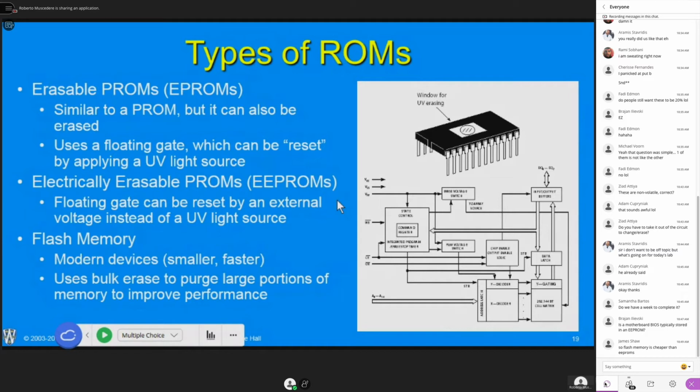So again, if you guys have these micro SD cards, you'll note that the write speeds aren't really fast. They're not like solid state drive fast, right? Again, solid state memories or solid state drives are a compromise of, well, how do I get flash memory and speed? So they do a lot of stuff in parallel. They'll have parallel memory chips. They'll use a lot of wear leveling. The system is always trying to erase unused sectors so it can write to it faster. There's a whole song and dance going on behind the scenes to make them operate as fast as possible.